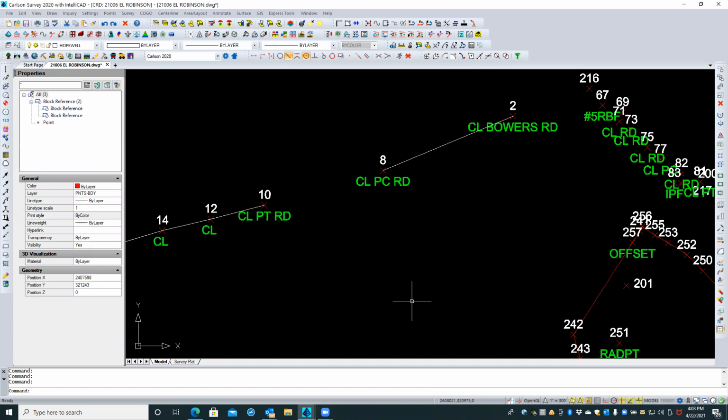If you do not declare a point as a PT, it assumes the one where it starts with PC, it assumes the next 2 points define the curve. Okay, so it will fit an arc between those 2 points. I didn't shoot a center line between the PC and PT. And that's okay. That's one of the other ways it can work.